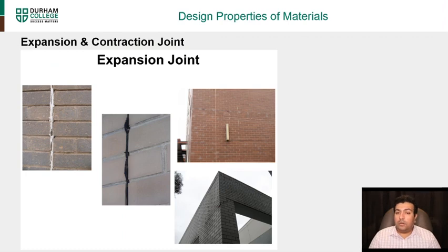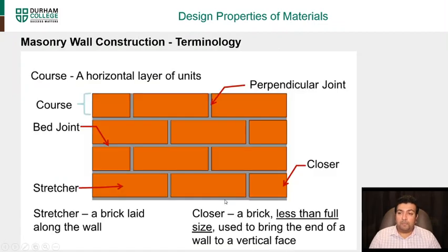So you can see here are more examples of the expansion joint, right? Because it's expanded, it's coming out or bulging out. And here you can see, because we did not put an expansion joint, the edges are moving out. That's why usually you'll see if it's a long wall and close to the edges, you'll find expansion joints in buildings to avoid this situation happening.